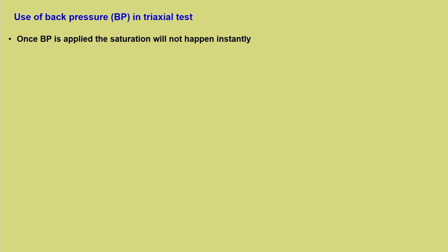This also we need to understand. When a load is acted upon the soil, we say that immediately the water captures all the load. Yes, this is true, but there is a bit of time lag by the time it delegates to the entire soil sample. So, once the back pressure is applied, the saturation will not happen instantly, it is not an instant response.